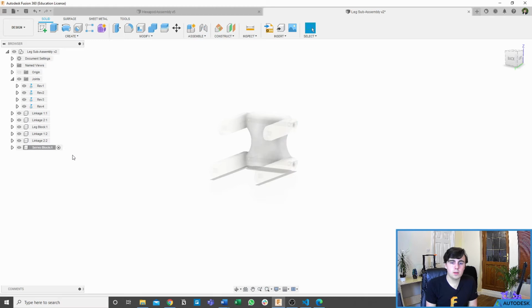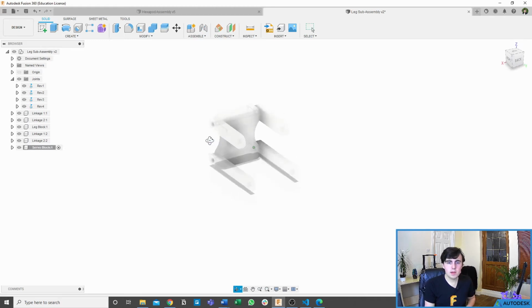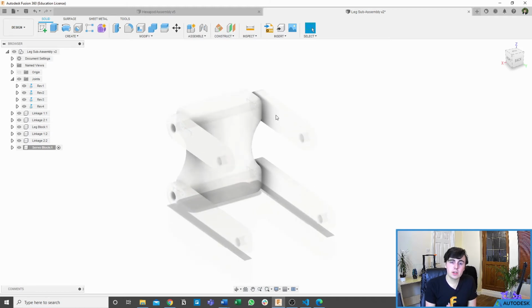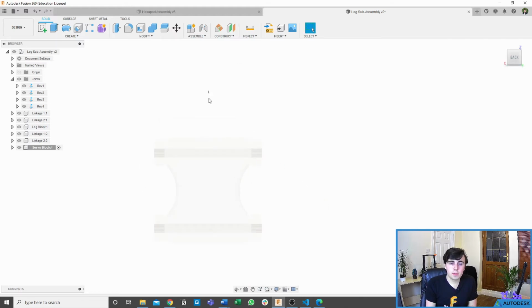You'll see it appear down at the bottom, and we want to create a sketch that goes between these two parts. We're actually going to do this slightly differently than we did before. We could theoretically create a sketch on this side profile, but I'm going to do this slightly differently to show you some other methods that you could use. In this case, we're going to create a plane down the middle of this part. If I look at it from the back, we're going to create a plane down the middle here, and then have our extrude go out symmetrically on either side.